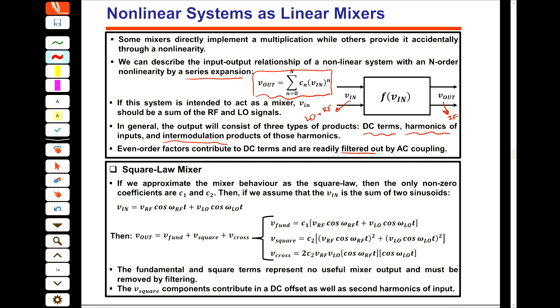But in the lab, actually, you don't need that much of the concepts and different types of the mixers. But what you are going to measure is what we covered in lecture 3. You need to measure the IP3, P1 dB, and then the harmonics.